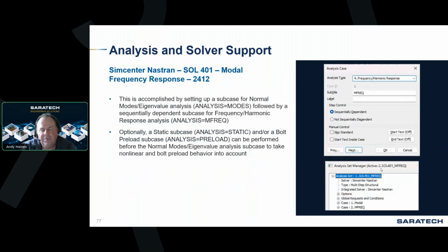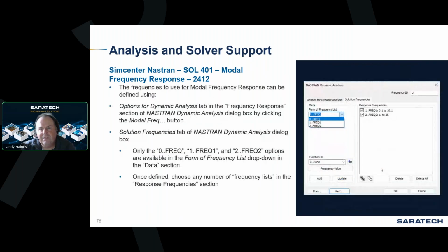If you're using solution 401, we added support for modal frequency response. This is one of those things where it's kind of easy to set up, but it's a little different than doing it automatically. You do need to create two subcases, one a modes subcase, and one that is sequentially dependent, which is analysis equals mfreq. But all of what is needed to do that is now in the analysis set manager.